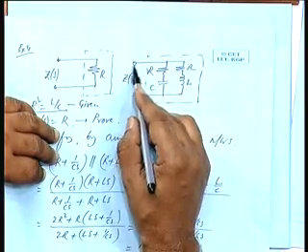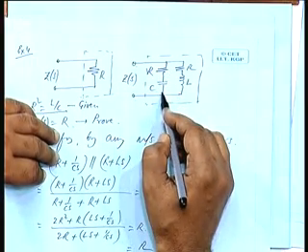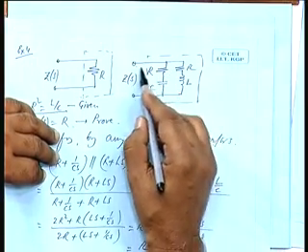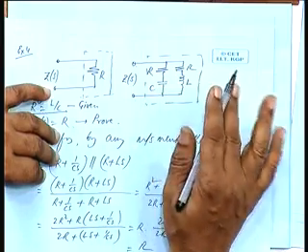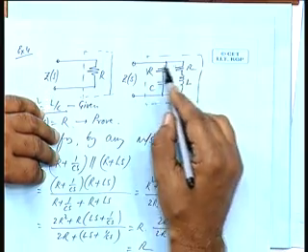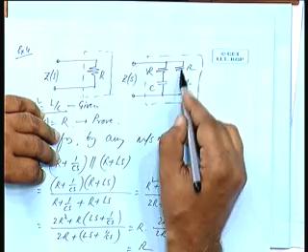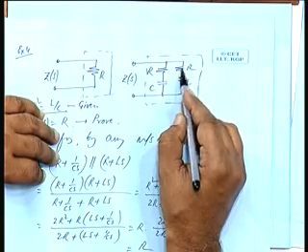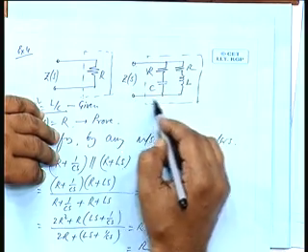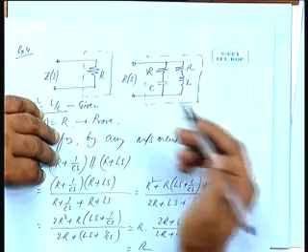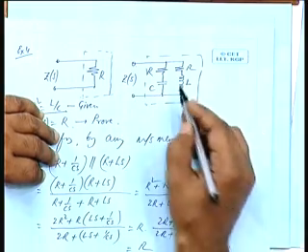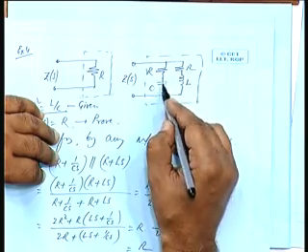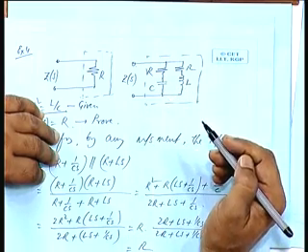In this circuit, this will get charged up to V volts and there will not be any drop across the inductor because current will be stabilizing, no di by dt. So, the entire current will flow through R, this R, is that all right? So, there will be a current through this, is it not? These are two energy storing devices, all right.